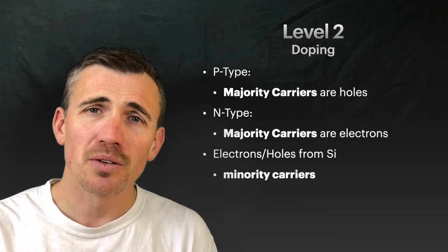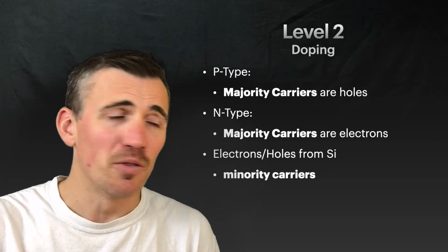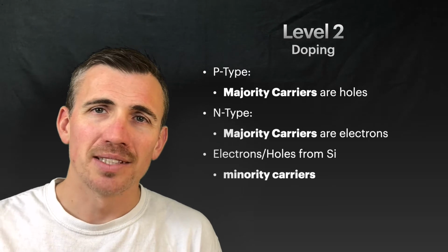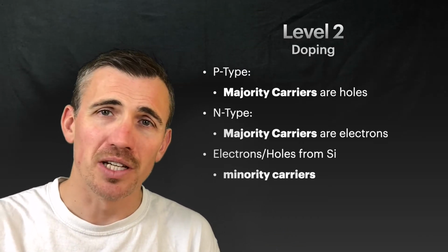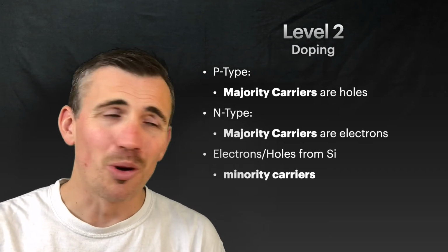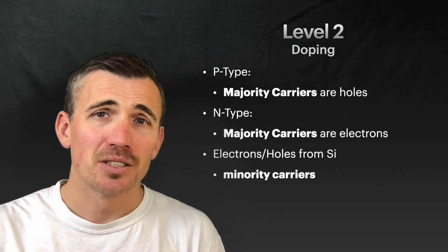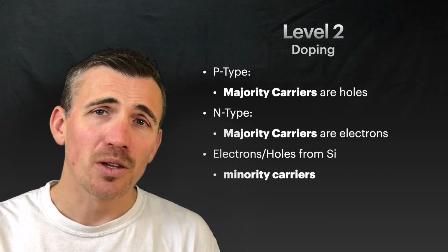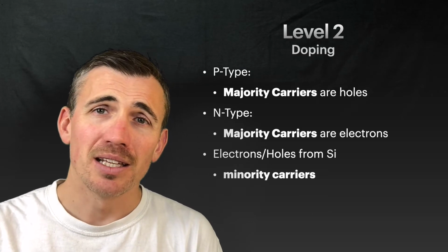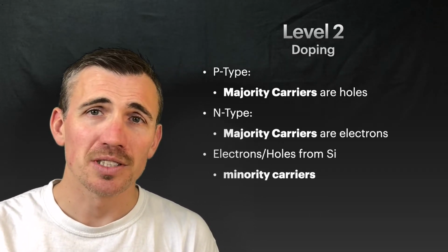So kind of a picture of what's going on so far is we start at like 0 Kelvin. Nothing can move, not even the holes and the electrons. 1 Kelvin, 2 Kelvin, same thing. There's just not enough thermal energy to shake even the electrons and the holes free from their boron or phosphorus atoms, whatever we're using. But it doesn't take much. So at very, very, very low temperatures, even a doped semiconductor, p or n-type, is a perfect insulator. As we start cranking up the temperature, we'll start seeing some interesting stuff.